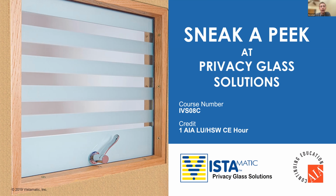Okay, great. And then can the electric glass be used in a wet location like a shower? It can, but you definitely have to be careful on how it's installed. I think the term that's used is a wet glaze or a wet seal, where the edges of the glass have to be protected, and there cannot be any condensation or moisture that penetrates into the edges.